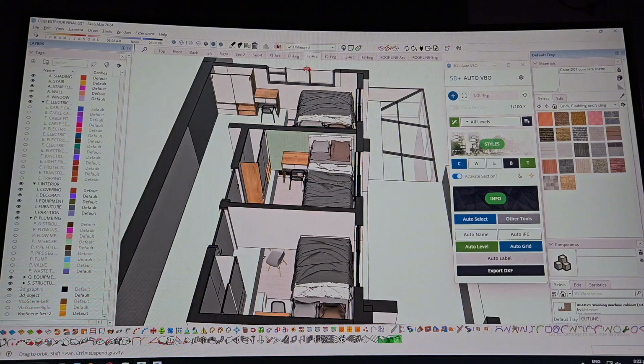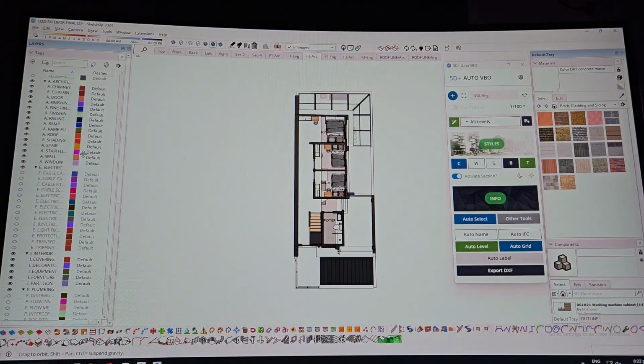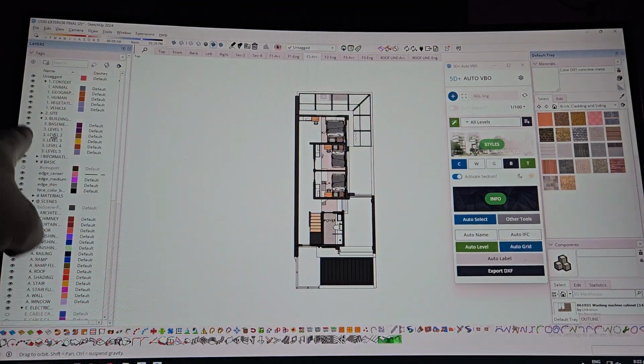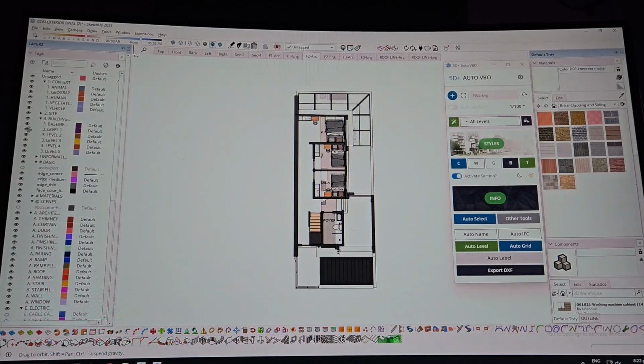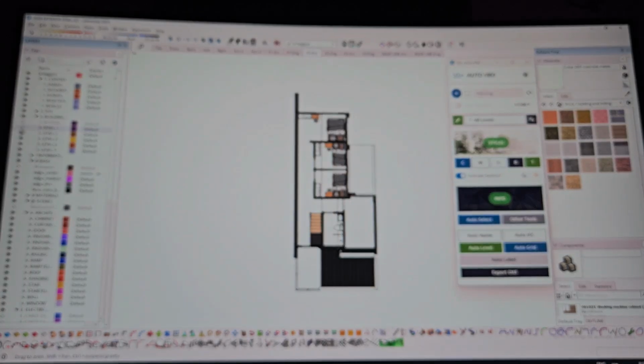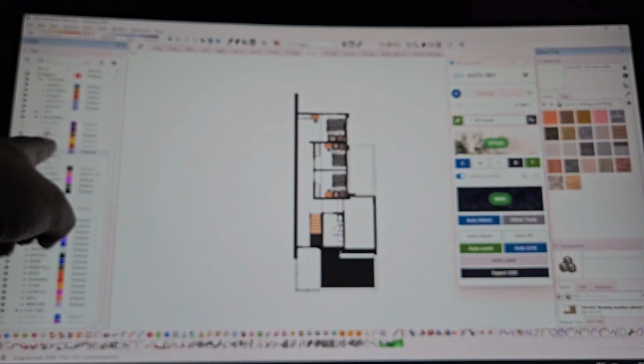Okay. So for F2, I actually want to hide everything below. So I go here to building stories level. I had a basement, level 1, and level 3, 4, 5. So only level 2 gets visible. Update that. Or Shift 3 for my update.